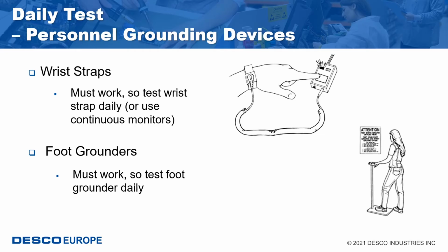The European standard requires that wrist straps be tested on the person at least daily or monitored continuously to determine that no break in the path to ground has occurred. When seated at an ESD protective workstation, a person must be grounded via a wrist strap. In some locations, such as the wave solder or test areas, wrist straps may be too confining or unsafe to use. ESD protected footwear or foot grounders may be used on an ESD floor to remove charges from the person to ground. It is critical that foot grounding devices maintain constant contact with a properly grounded conductive or dissipative floor.